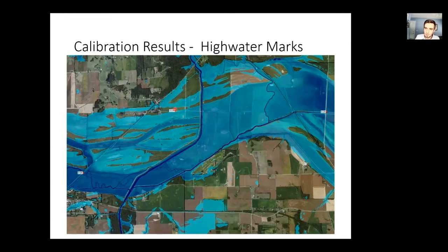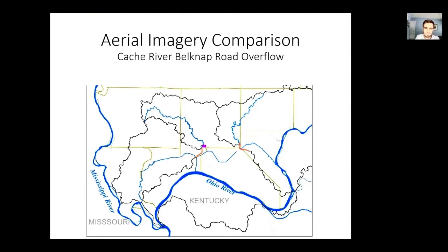And what we're showing is that our peak 2D model results for this calibration event are pretty much hitting right on the observed high watermark elevations. And then here on Main Ditch, our 2D model is coming in about 0.3 of a foot higher than the collected high watermark. So we're really quite pleased with these results, especially in this area of the model.